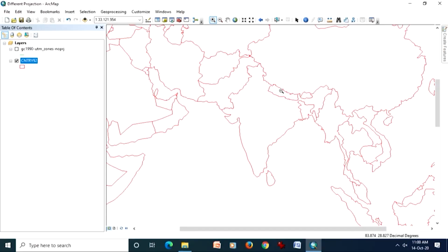After georeferencing of raster data also, it would create no data. So the best solution is to assign no color, and that way it will mix with the background, and it would look more realistic and nice as well for presenting, either through PPT or printing or other things. So it is always better to handle these things.